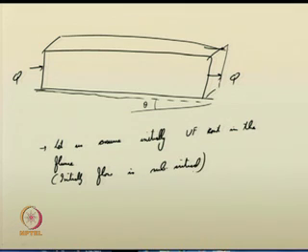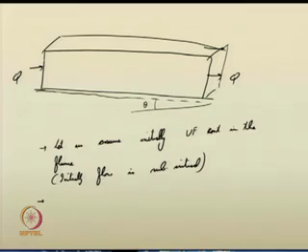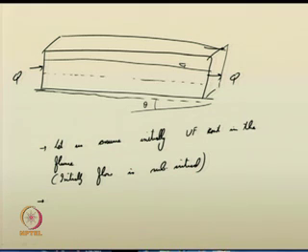Okay. So, if we increase the slope of the bed now, you will see that the normal depth of the flow in the channel will start decreasing. Say if this was the normal depth initially, and this was the critical depth computed for the particular discharge in this section, then you will see that if you increase the slope, the normal depth will decrease.